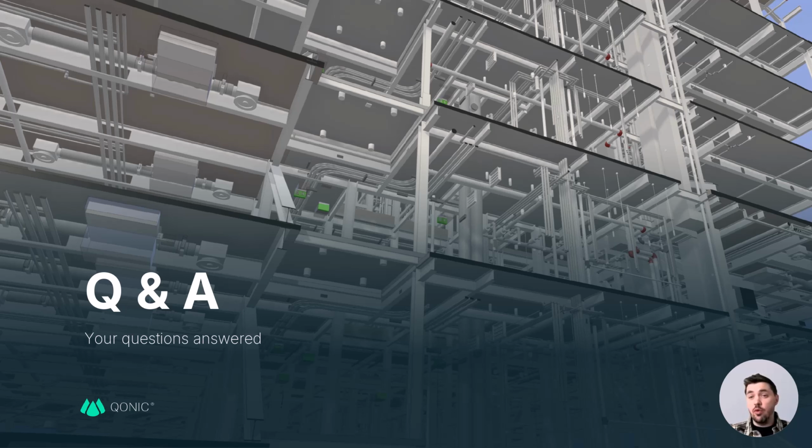In terms of some of the more popular file formats like Revit, and as per your question, Peter, you can bring Revit information into Qonic, and you can currently do that in two ways. One is if you install the Qonic plugin to Revit, you can open the Revit model, visit the Qonic plugin, and press export, and it will push that project to Qonic. This is really good if you have extremely complicated projects that are billions of polygons, and it will churn through that pretty quickly.